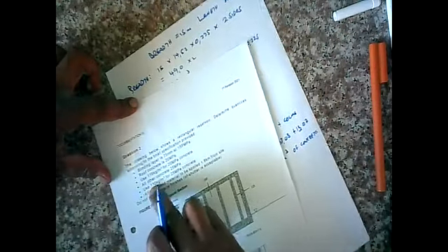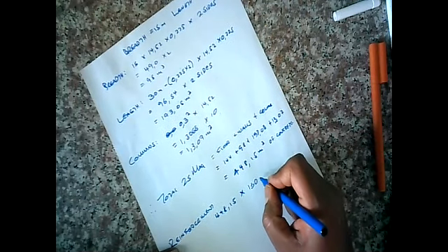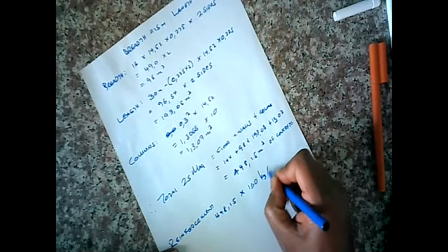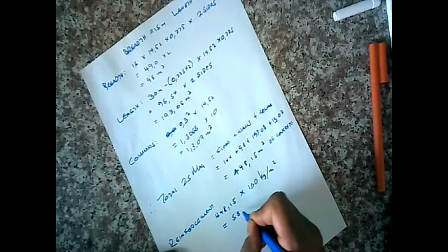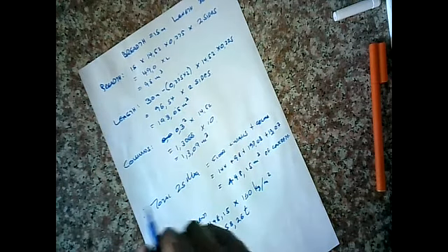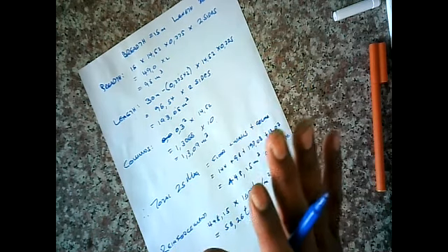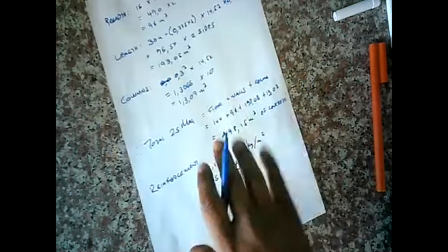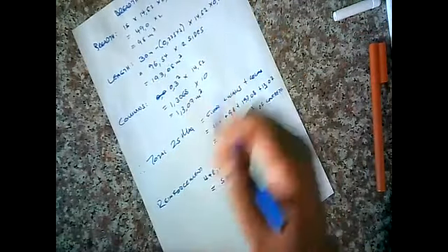25 MPa use 130 kg per meter cube. And we're finding it to be 58.26 tons. Right, remember from the lecture, steel is in tons. Right, now we've put on the roof, we put on the walls, we put on the columns. What's next? Let's put the roof on.